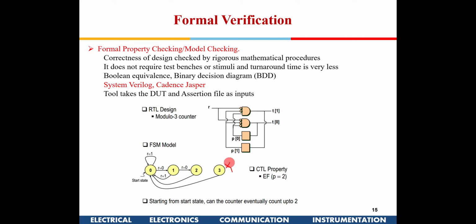How to do a formal verification of this? If you want to do a proper check, you will have to take this pattern, this pattern, this pattern, and so on. Instead, if I take the first pattern 0 0 and see that the next pattern is not equal to 0, and after 3 clock cycles I am getting back 0 0, you can fairly assume that this is a counter which is working perfectly. You don't have to verify if the second one is 0 1 or 1 0 at the system level.